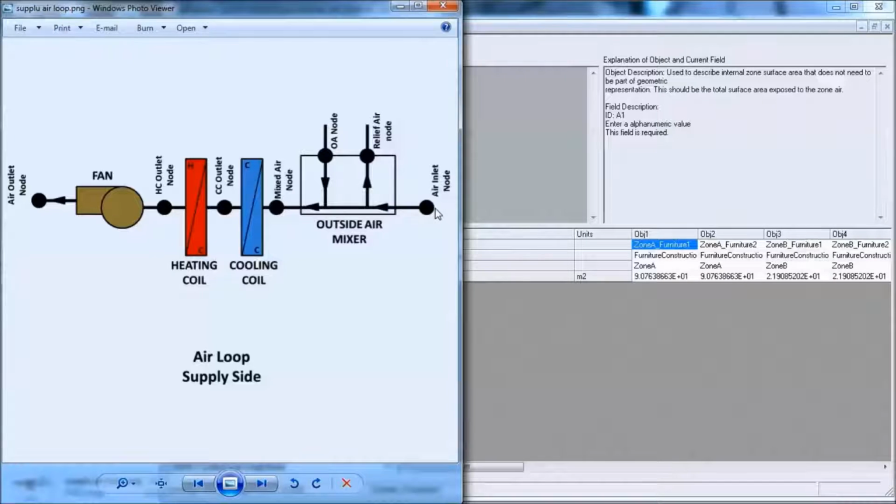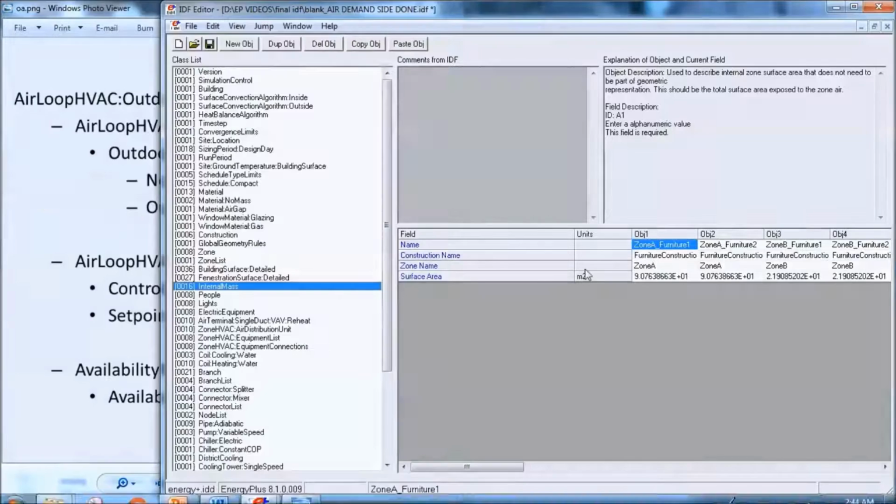The air flow would be from air inlet to air outlet, with no air exchange between these two nodes. The middle situation can be different percentages, controlled by moving the damper, which controls the volume. So this is the basic function of an outdoor air mixer.